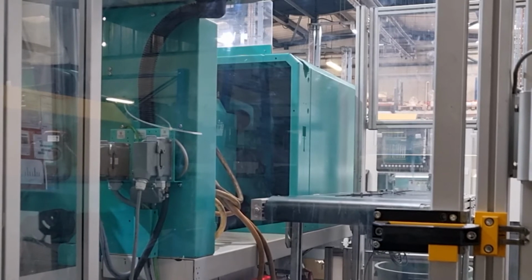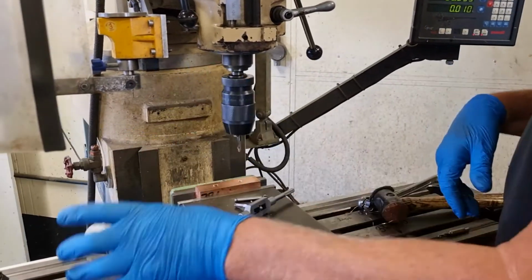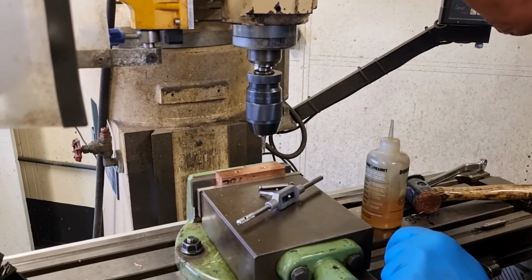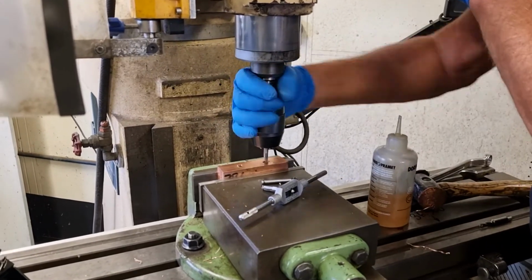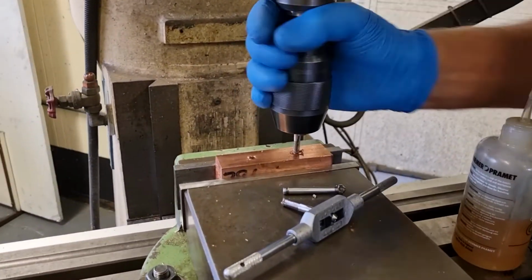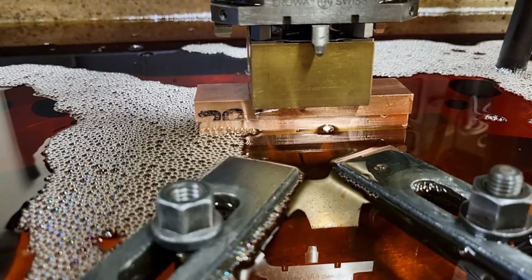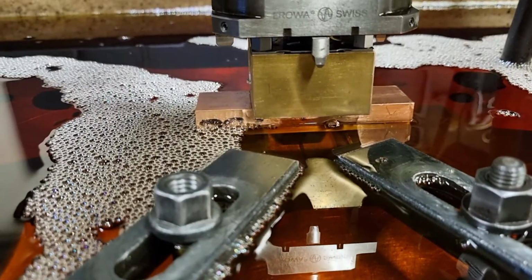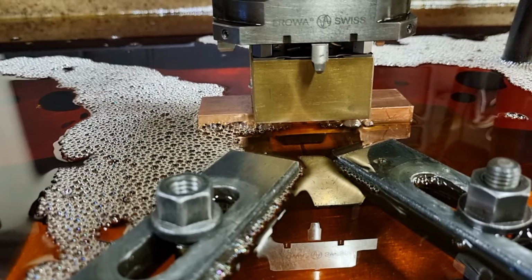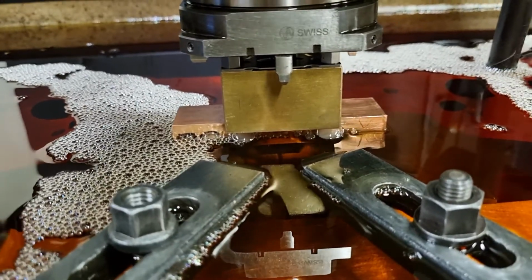One downside to hot runners, beside the energy usage, is the maintenance of hot runner mould tools. With cold runner systems, the issue can usually be rectified with machining or EDM machining. Because of the complexity of hot runner systems, the maintenance can take a lot longer and be more expensive.